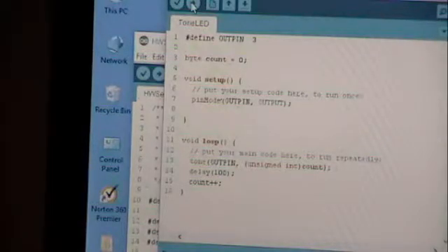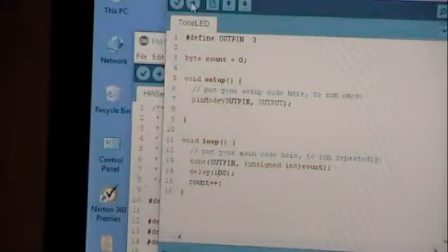How do I put this? A signal that you would see is a combination of signals. DC is every frequency at the appropriate levels. A tone is a single frequency. It's a sine, but we're talking frequencies and sine waves. When you make a square wave, there is a fundamental frequency. So if I say, using an easy number, 10 hertz, a square wave has a fundamental of 10 hertz.